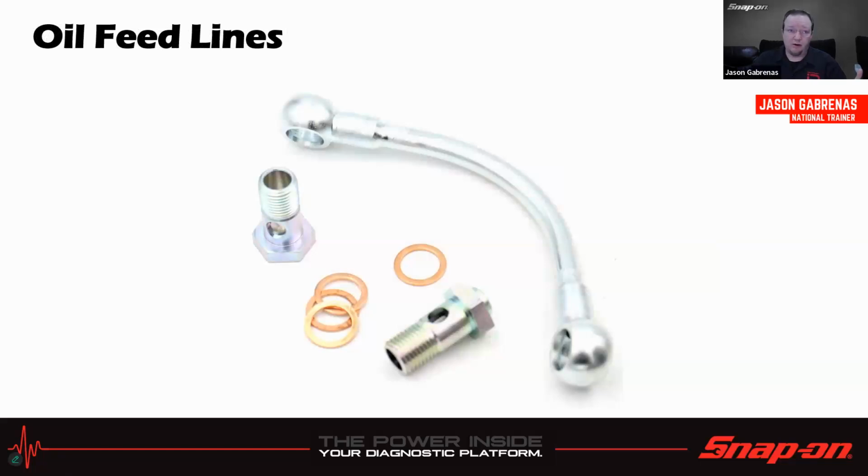And then we also need, of course, to be able to get the oil to this because it's oil actuated. So we need oil feed lines as well. So oftentimes you'll see just the metal lines. Could be some rubber involved. And then, of course, you have these banjo bolts. Some of the banjo bolts will have a filter in them. Usually the ones with the little nub at the end are going to have some sort of a cleaning filter in there just so no gunk and crud gets into the actual system itself or into the gears, or at least it tries not to get into the gears.